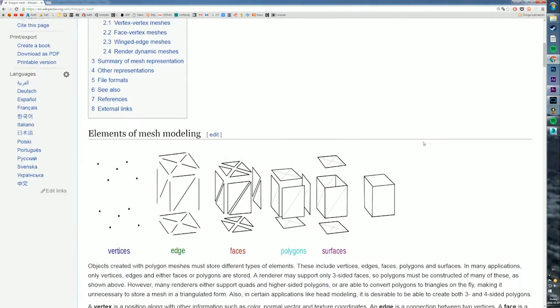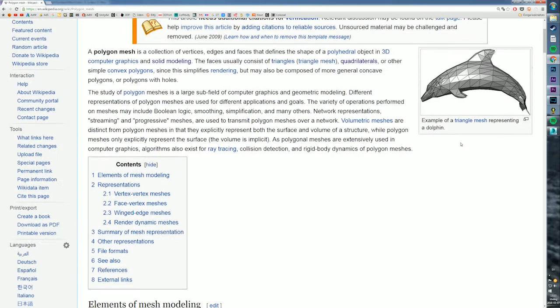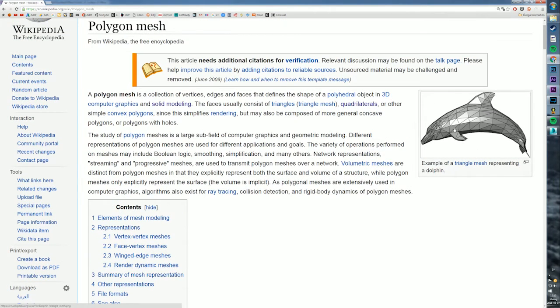So you define a shape by using a resolution, much like a picture is defined by its resolution. So you have full HD, you have 4K, and so on. The more details you have translates to the more polygons you have. Another interesting thing about polygons is that if you zoom in, you will end up with a flat surface. When you have a solid or a surface model, you can zoom in infinitely, and you won't get this barrier of resolution in the same way.